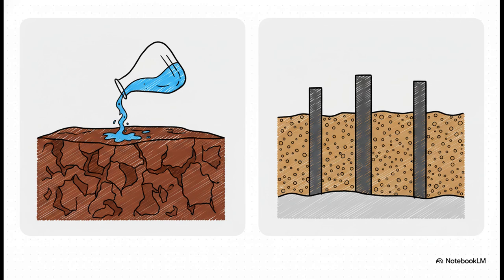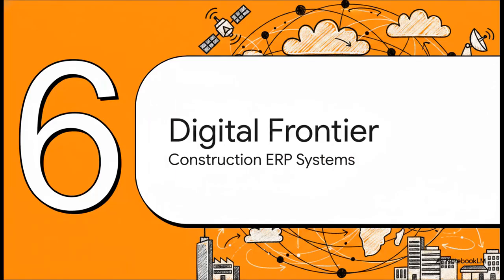But beyond the math, you also have to dynamically troubleshoot the earth itself. Soil is wildly unpredictable. Clay soils will swell up when wet and shrink when dry, which means you have to use chemical stabilization. Sandy soils, well, they drain beautifully but have zero cohesion, often forcing you to drive deep pilings to reach firmer ground. As a site engineer, you are constantly mediating a tug-of-war between structural needs and these crazy ground variations. Finally, Section 6.